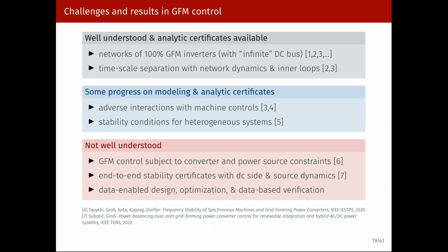Yeah. Sorry, I'm a control systems person by training. So for me, stability means Lyapunov stability, which basically means if you start the system near its nominal operating point, it stays near the nominal operating point and doesn't blow up. So frequency going unstable would mean frequency escaping to 0 or to infinity. Whereas if you can keep it inside of the nominal operating region, that's something we would call stability, and then we would call it asymptotic stability, where after a perturbation it even goes back to the nominal operating point exactly.